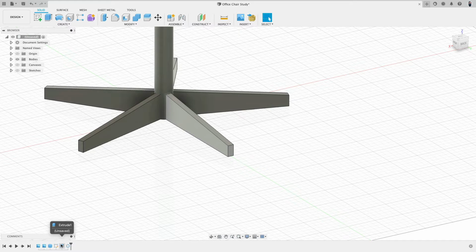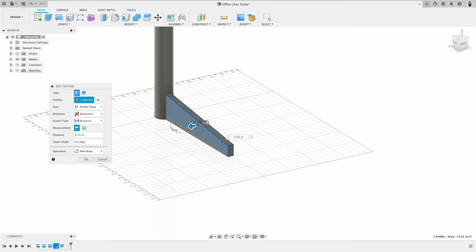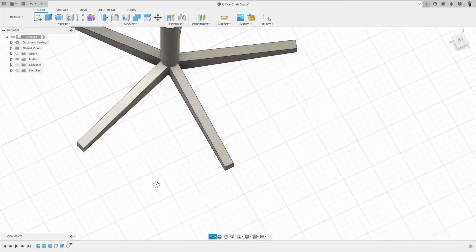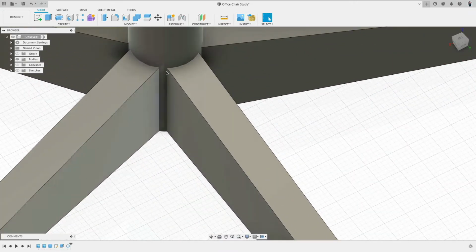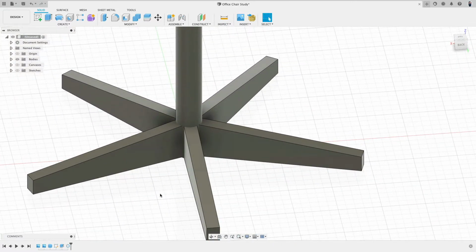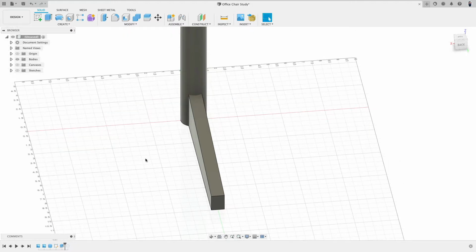I would like to change everything a little bit. So let's go back to here. So I double clicked on that extrude command and say the whole distance maybe be 7.5. So the whole length, I mean. Okay, so there we see it's getting very close. Okay, good. And then I will go one time back and I also will hide this one.